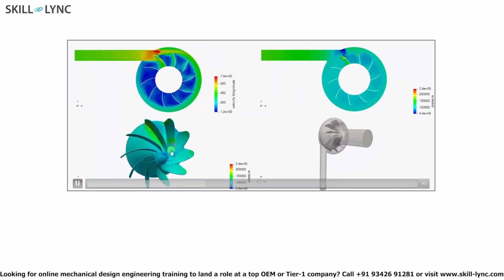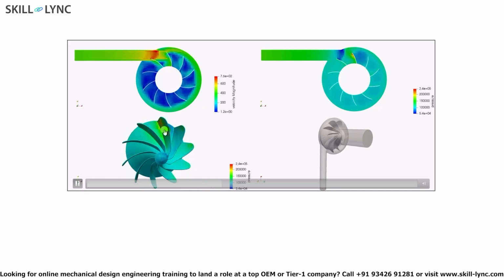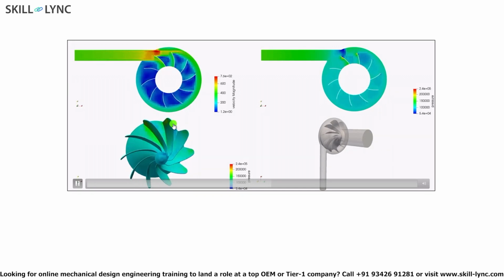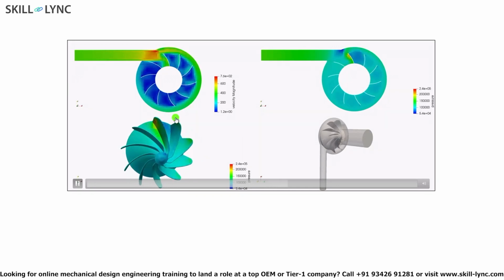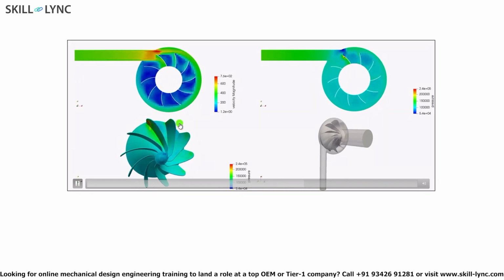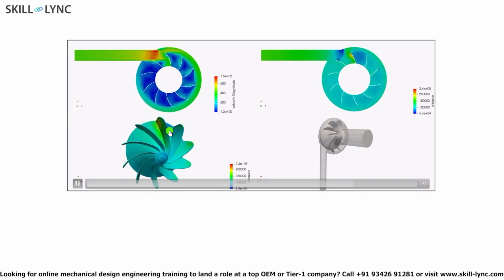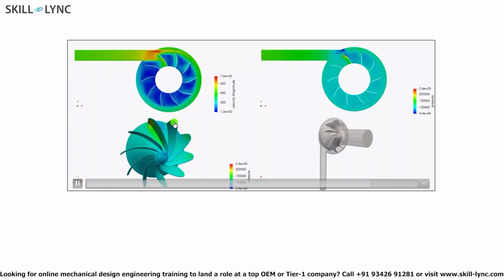And similarly in this plot, you're actually looking at the pressure on the impeller surface. Now this actually tells you a lot of important insights. First is you can see that the impeller is not uniformly loaded. One side of the impeller is always loaded more than the other side, so there is asymmetry, so the loading is basically non-symmetrical. This might be relevant for FEA simulations.